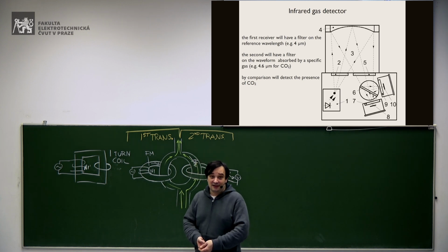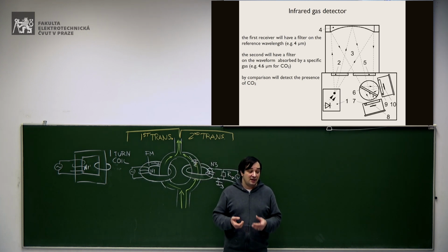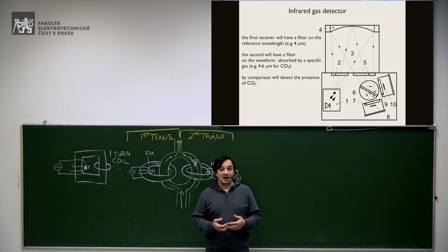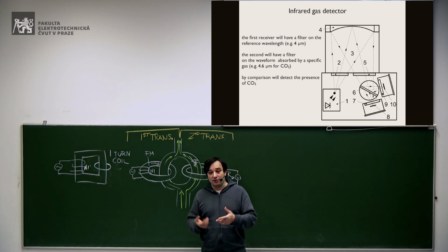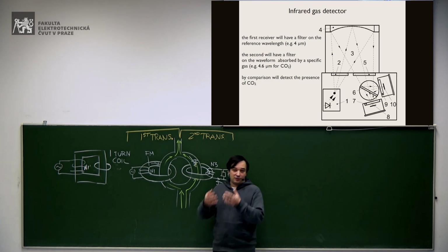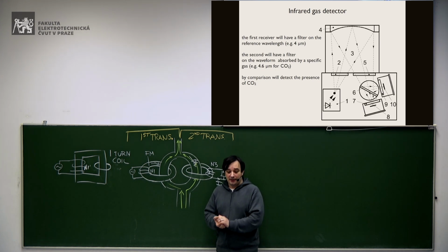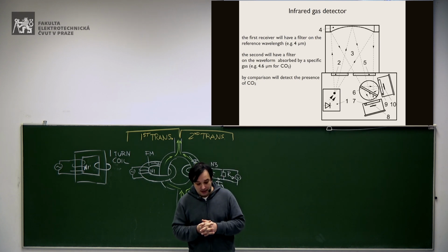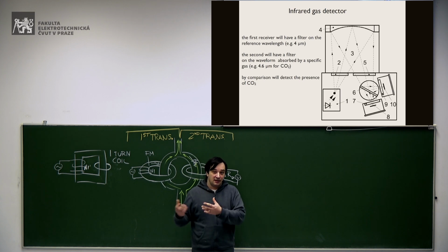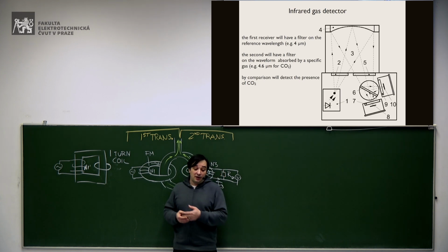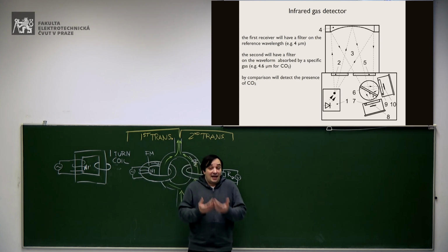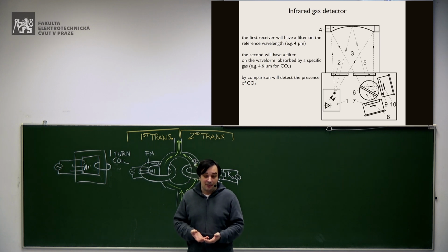The signal that you see at the detector at 4.6 micrometers did not decrease because we have an increment of the carbon monoxide, but because, for instance, the source of light, the source of radiation, decreased, okay? So, how can you avoid having this misleading result from your detector? You always have another detector at 4 micrometers, which doesn't react with the carbon monoxide.